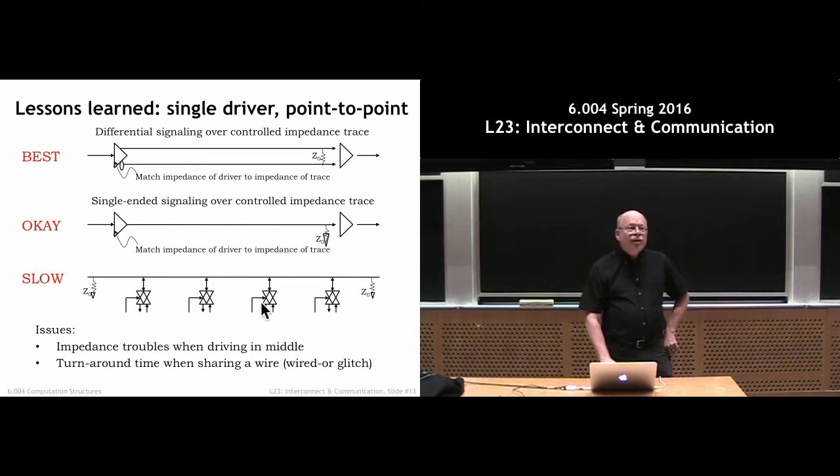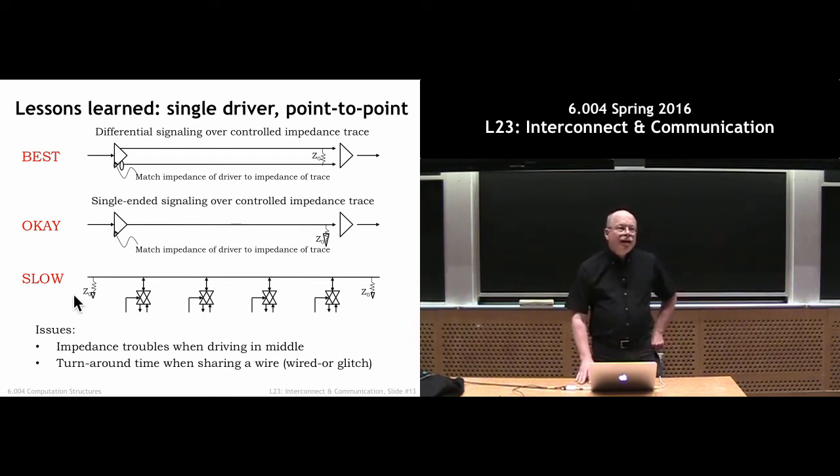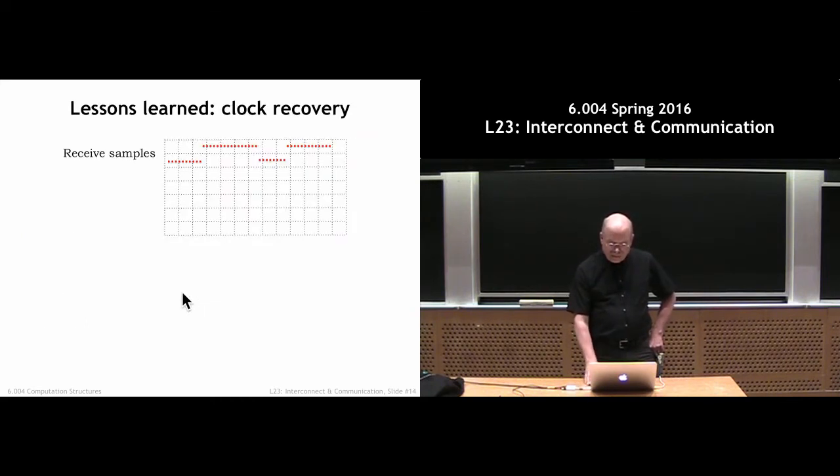The worst thing you can do is to have a single wire that's shared among multiple drivers. There are all these electrical issues with impedance problems, and the fact that depending on who's transmitting, people receive slightly different waveforms. This is not a good idea in the modern era.